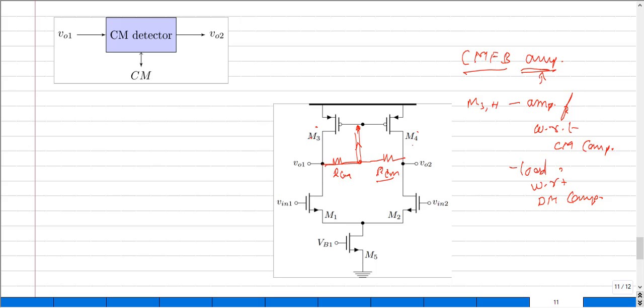Yeah. So coming back to our analysis, this particular circuit, that is the feedback network that we have drawn here, has two major issues. One is that the inclusion of these resistances basically lowers our differential gain, because these resistances actually load the output node. When I apply a differential input, the outputs are also differential, and due to which this node can be considered as connected to the ground. Now when I look across this node and look for the output impedance, what I have at the top is nothing but RO3, and when I look down it is RO1, and then I also have one more resistance in parallel to RO3 and RO1.